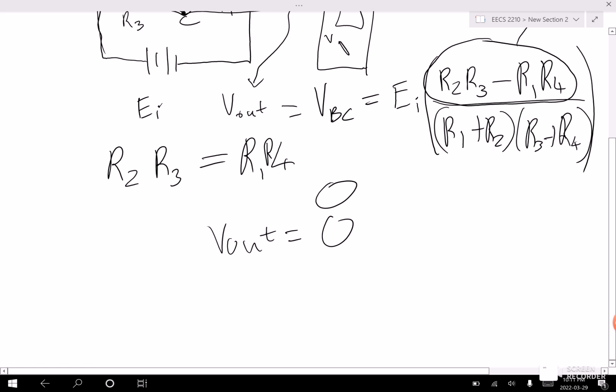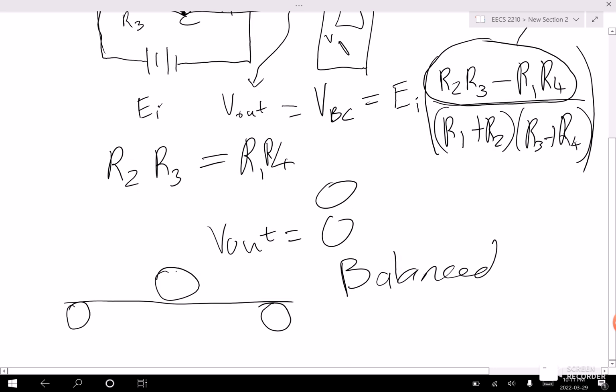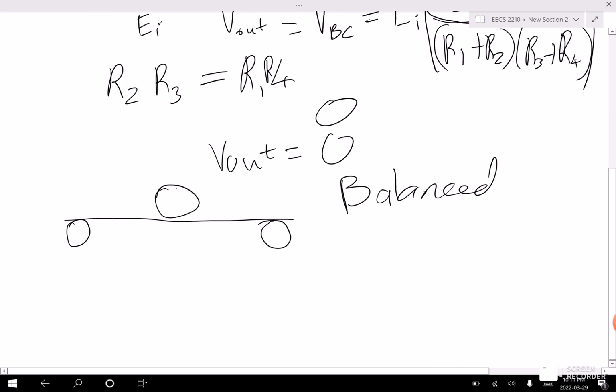And this tells us that, imagine our circuit being on this beam, and the circuit is this rock, and the beam is balancing the circuit, it tells us our bridge is balanced. And we want our bridge to be balanced because a balanced bridge is used to measure resistance change of resistive sensors, strain gauges, either using a null method or deflection method.